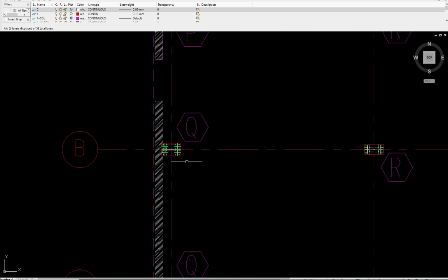Usually a base plate should have at least 25 mm minimum concrete edges outside the base plate, but for good workability one should have 75 mm of concrete edge available from the edge of the base plate. In PV structures I have seen the PV designers taking that to 150 mm, which is at times really not required.